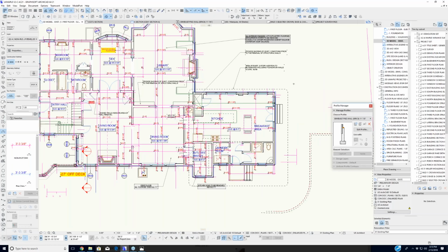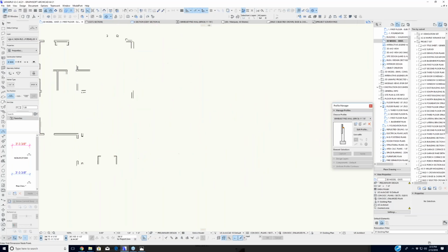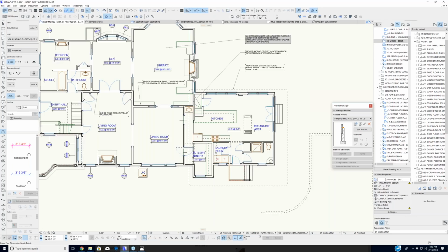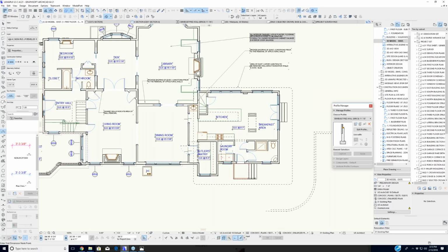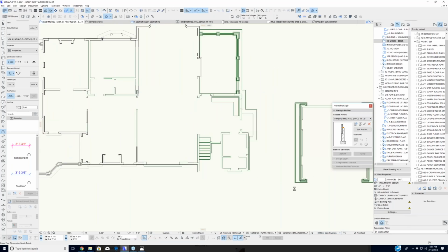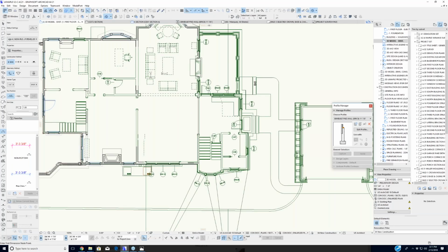I can see down at the bottom of your screen where you have the tab bar, yep, the existing plan. And if you were just to make the one single change from existing plan in the renovation filter and change it to new construction or plan status, go ahead and let's just see what comes up. Yeah. So right now you're looking at existing, which is showing, if I click over here, existing and demo. This wall is coming down. Now, this is not a demo plan. This is an existing plan. That wall, if I highlight it, is on the demolition layer. If I come over here to the renovation filter and say, now take me to new, you'll see that immediately changes.